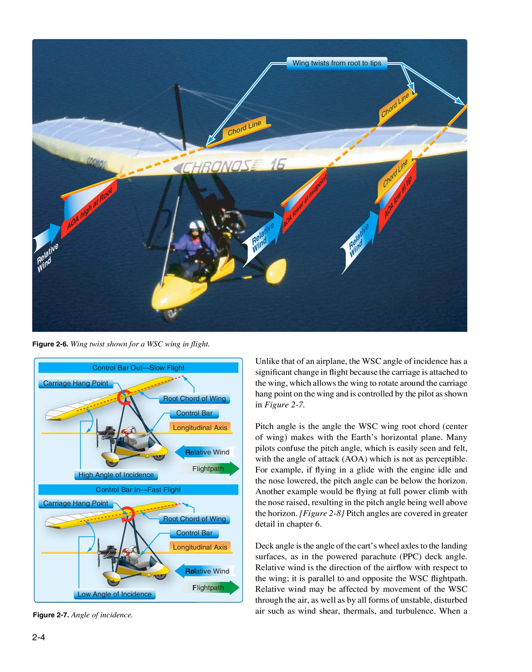Pitch angle is the angle the WSC wing root chord, center of wing, makes with the Earth's horizontal plane. Many pilots confuse the pitch angle, which is easily seen and felt, with the angle of attack, AOA, which is not as perceptible. For example, if flying in a glide with the engine idle and the nose lowered, the pitch angle can be below the horizon. Another example would be flying at full power climb with the nose raised, resulting in the pitch angle being well above the horizon. Figure 2.8, pitch angles are covered in greater detail in Chapter 6.